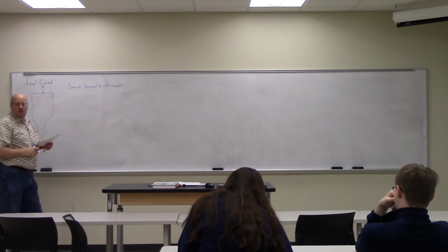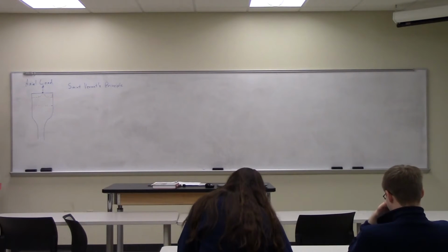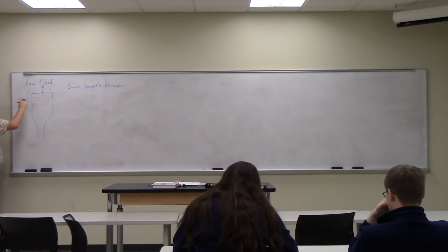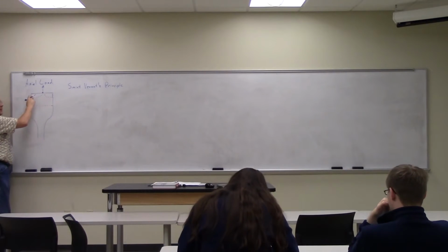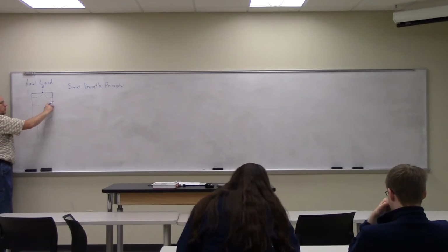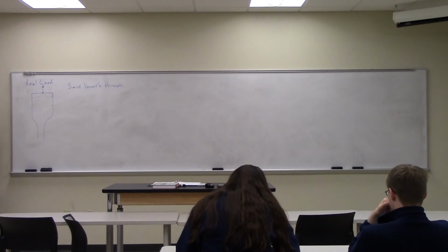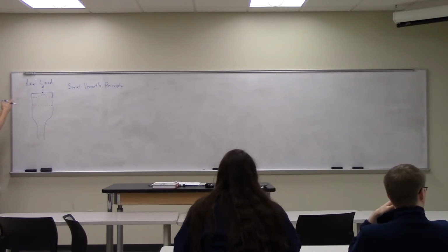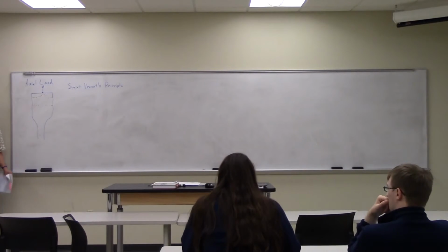Sorry, can you repeat real quick what those dotted lines are? Those are the stress distribution. So here I have a high stress in the center and a low stress at the edge. But as I get further away, the stress becomes uniform across there. So there are no numbers associated with that, that's just a relative distribution of stress.